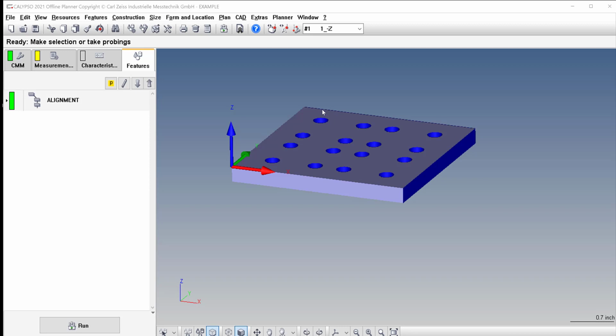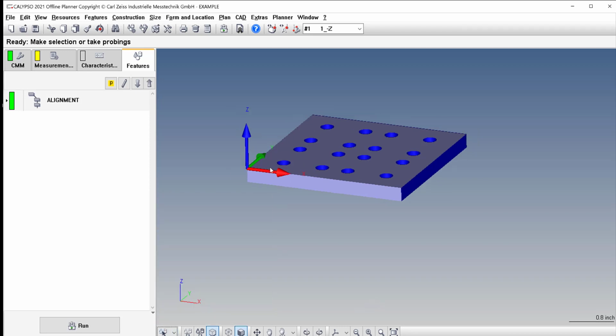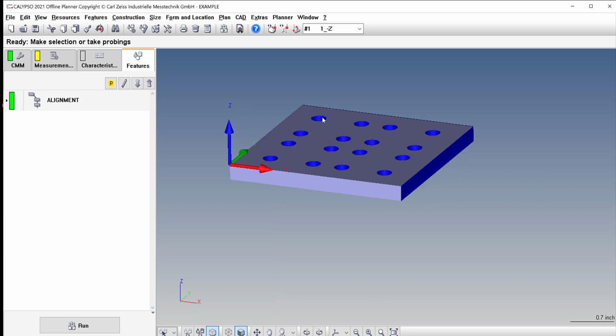If you just use define select geometry, it will default to cylinders, and we're not trying to capture a positional tolerance as far as the GD&T spec, and this is a little bit unstable, so we're going to create circles. The other thing is, the way I'm going to have this spec'd out in the report is hole 1, 2, 3, 4, 5, 6, 7, 8, and so on, and then it'll just be hole 1, X, Y, and diameter. That's the way I'm going to program this, as far as my characteristic listing.